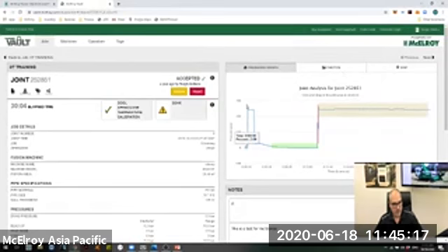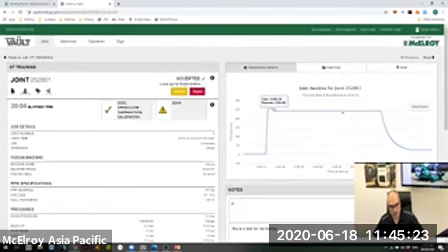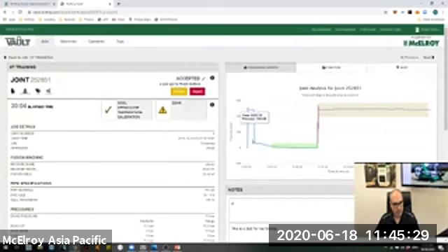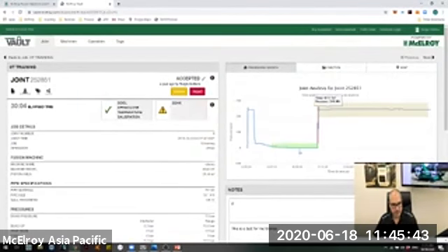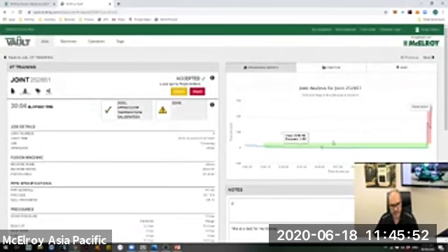Here, for example, we talked a little bit about this before. Here you can see your bead up. You can zoom into any of these specific areas as well, which is pretty cool and very easy to review. You can then reset your zoom. That green window is the heating time. So basically we need to check that that pressure is in the green window for at least the specified time in the welding standard.